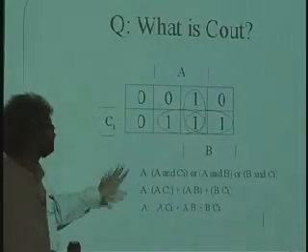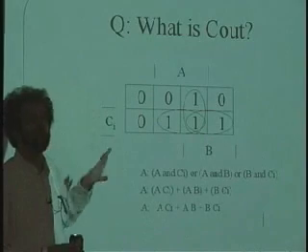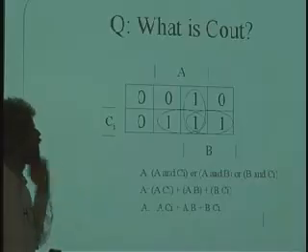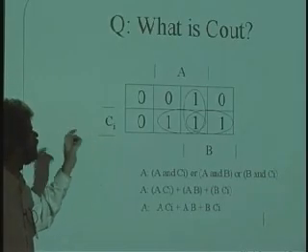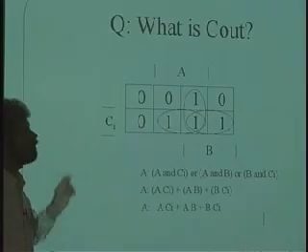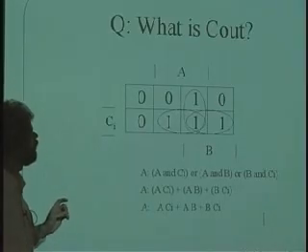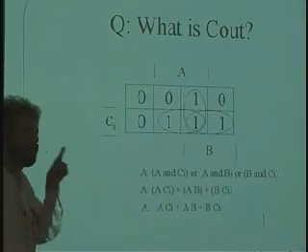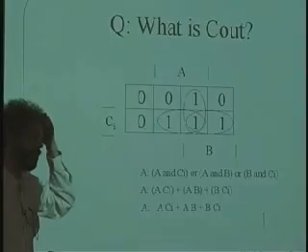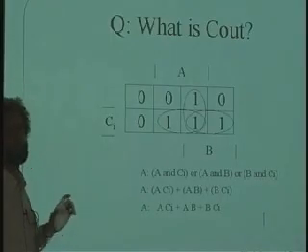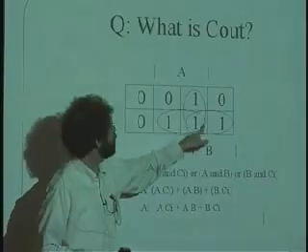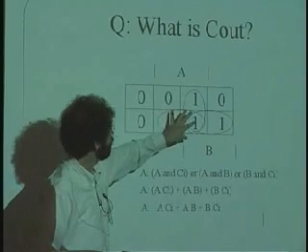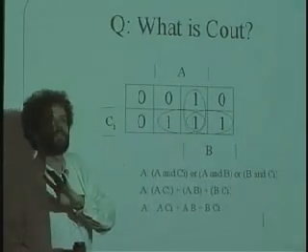Okay? What's wonderful is that this graphical technique allows you to simplify any sum of products form, anything where you have the OR of a bunch of ANDs, by coalescing smaller circles into bigger ones. Now, there's a few rules. The first rule is you can't make bigger circles whose size, whose number of ones they enclose, is not a power of 2. Now, why is that? Well, when I merge these 2 ones by changing it from a circle that's as big as a 1 to a circle that has 2 things in it, I eliminate 1 variable.